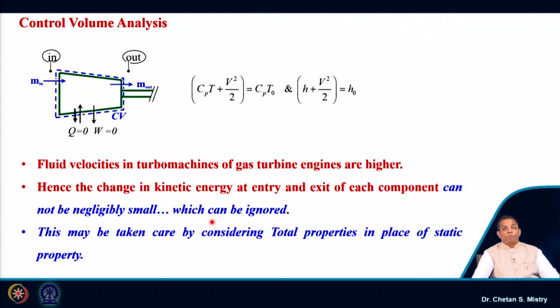So, let me put the point here. When we are analyzing our gas turbine engine, for our cycle analysis, we are not interested in static properties: not static temperature, not static pressure, not static density. Whatever properties we discuss will all be total properties. So, this is what we need to keep in mind.